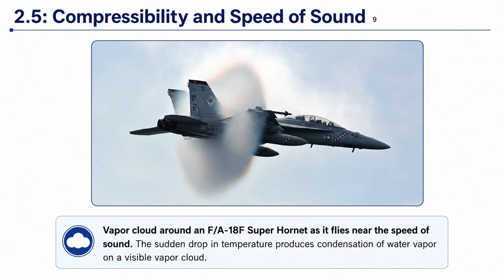This does not mean the aircraft is literally breaking a wall. The so-called sound barrier is not a physical barrier. It's a compressible flow effect where pressure waves, density changes, and temperature changes become very important. So this shows how important the compressibility effect is for high speed gas flow.